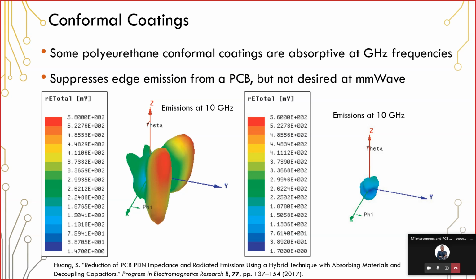That degradation could come from humidity, high temperatures, or exposure to noxious chemicals, like a corrosive agent that might exist in the air, or as a liquid. So conformal coatings are very useful, especially in high reliability PCBs. And so they are something that is important to consider if you're building something that's going to work in one of those areas.